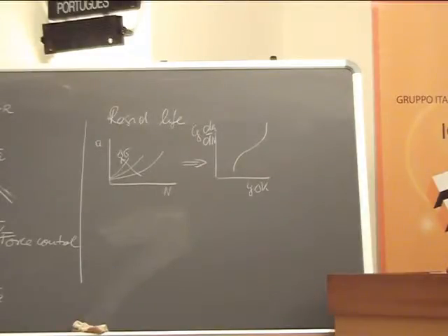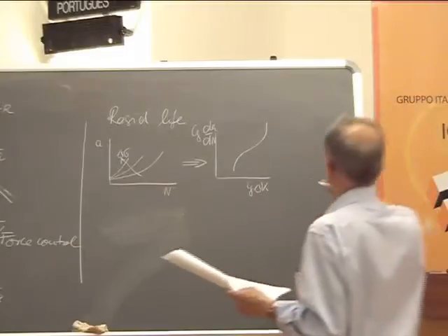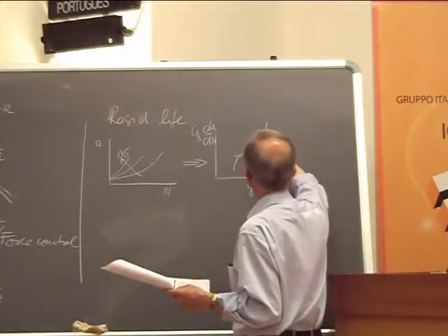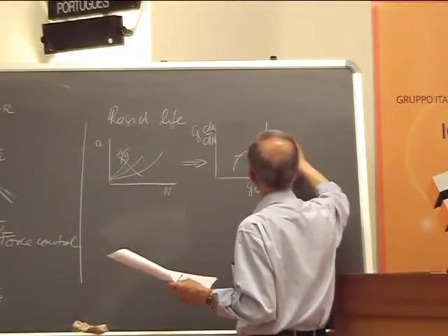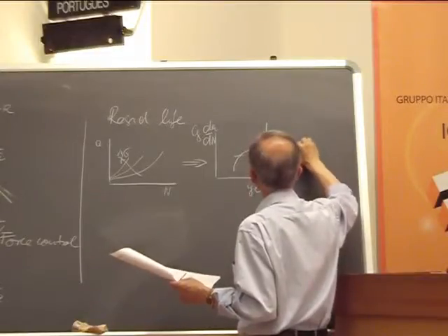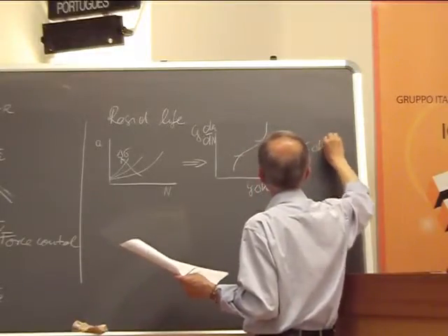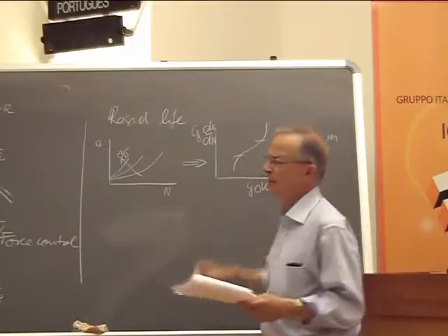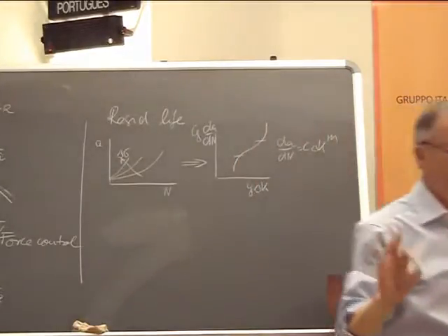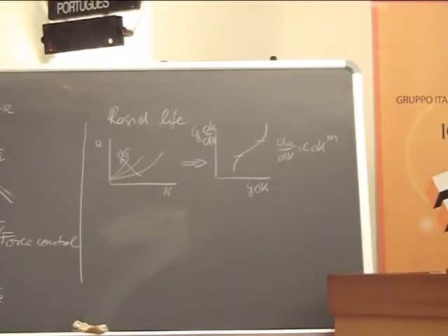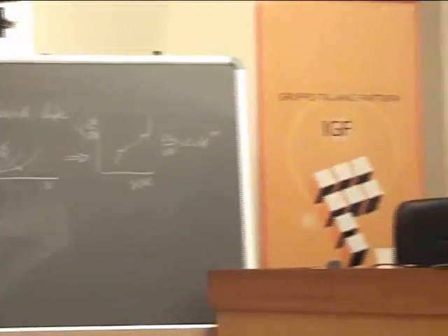And we have a crack propagation equation. For example, here in the middle is the center region where we have the power law, the da/dN. The da/dN is C times delta K raised to the power of m. Once again, the power of m is mostly between 2 and 4, not exclusively, but mostly.